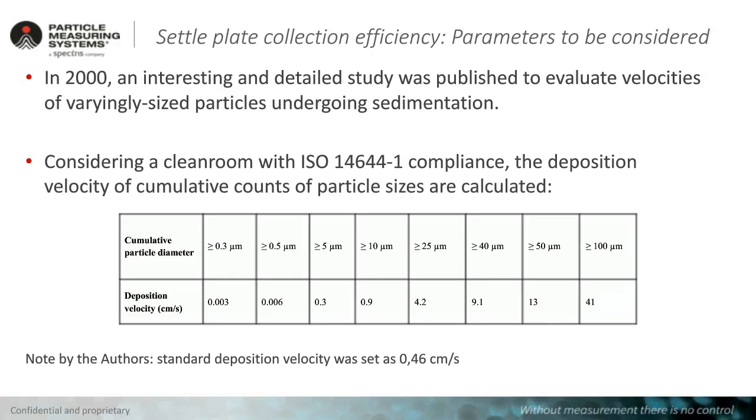Looking at the results from these experiments, in 2000 a very detailed study was published to evaluate the velocities of varying particle sizes in terms of sedimentation on surfaces. When we look into a clean room classified according to ISO 14644, the deposition velocity of the cumulative counts of particle size can be calculated. What you see here is that the velocity increases dramatically when you go above 10 micrometers, and of course it depends on the size and weight of the particles.